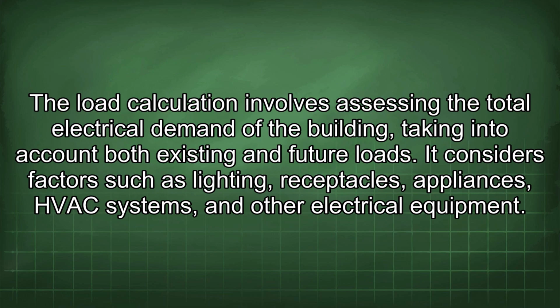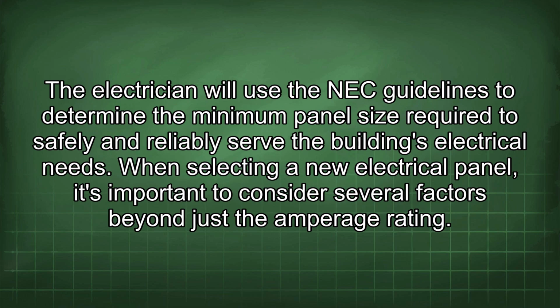The load calculation involves assessing the total electrical demand of the building, taking into account both existing and future loads. It considers factors such as lighting, receptacles, appliances, HVAC systems, and other electrical equipment. The electrician will use the NEC guidelines to determine the minimum panel size required to safely and reliably serve the building's electrical needs. When selecting a new electrical panel, it's important to consider several factors beyond just the amperage rating.